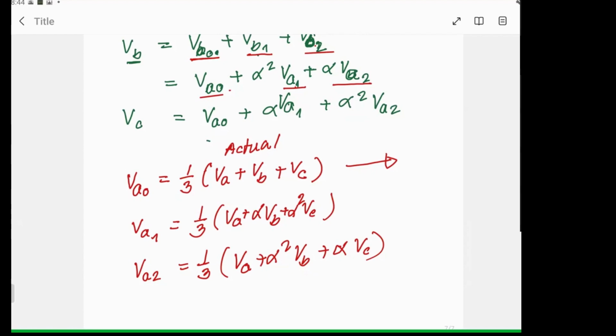Just without the calculations, purely looking at the vector diagram, you can see, like when you drew the fault on that system, that these two phases are going to drop and the other phase is going to shoot up. So you can say, this is this type of fault, I know this phase is going to shoot up and the other is going to drop down.